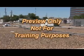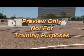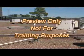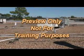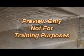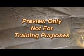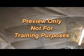In high heat areas, such as around production equipment, the use of specialized exhaust ventilation systems to remove heat or moisture is recommended. Finally, using reflective shields can help redirect radiant heat along with proper insulation.